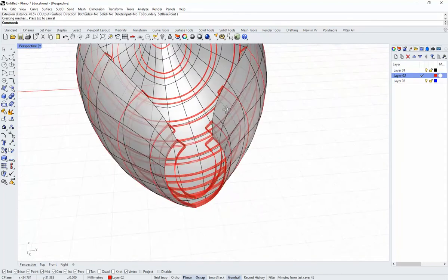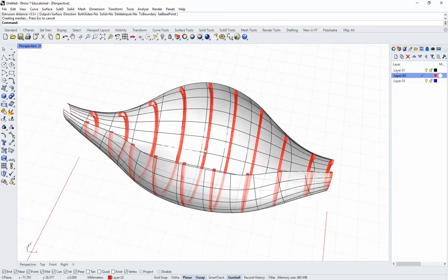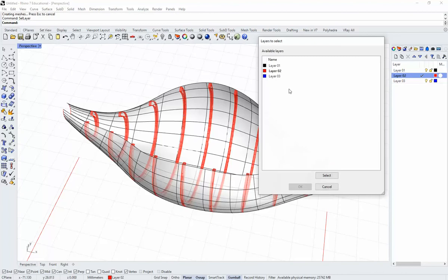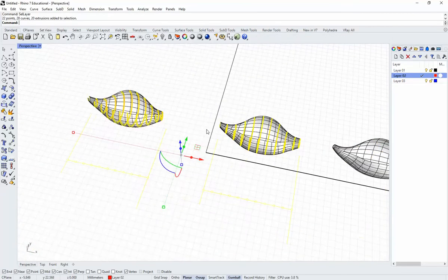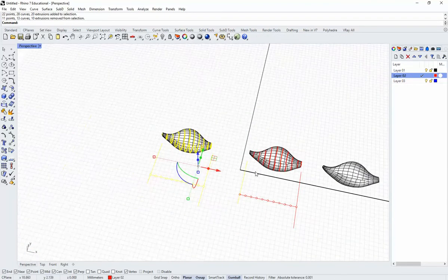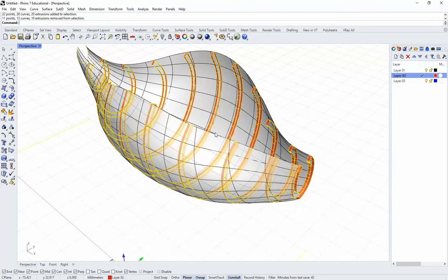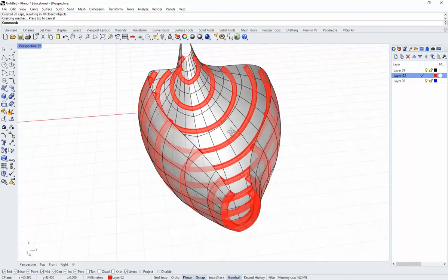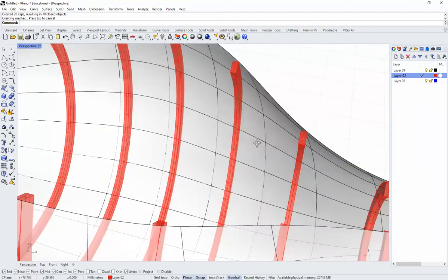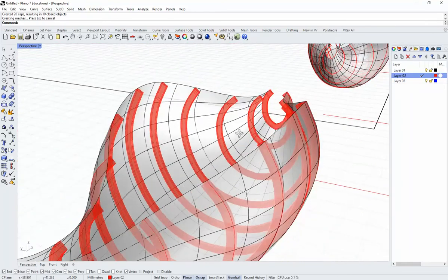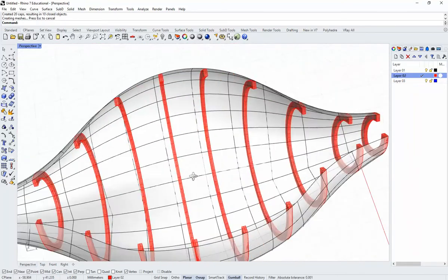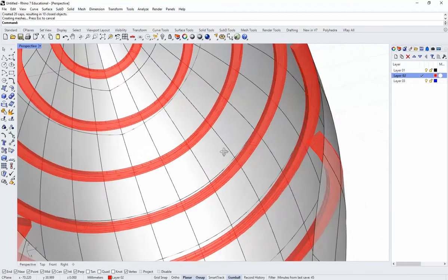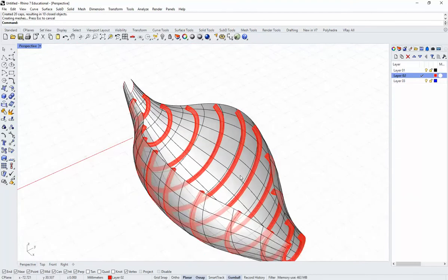Okay, so there's that. We should now be able to just select, let's go ahead and select layer, and I'll deselect some of this other stuff. And you can just type in cap, and that ought to force them now to be, it'll rebuild that planar surface in there for us automatically, so we don't have to do it manually. And because they're planar, that works. You can cap planar open poly surfaces, and it should add a cap to it. In this case, it'll add the front and back profile surface.